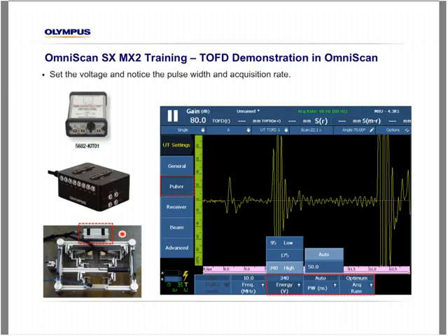The shorter the cables are, the less the need for these, using some of the older modules that didn't have as powerful a pulser, or using phased array connector to generate TOFD groups at a lower voltage. We can improve the SNR, or the signal to noise ratio of flaw data, by use of these accessories. Generally, with 2 meter, 3 meter, or 5 meter cables, this is not necessary.